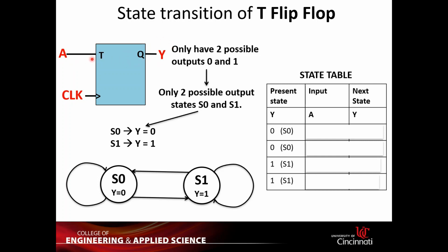If your input equals 1, it will flip. 0, hold; 1, flip. Piece of cake. So that means if I'm at S0 and my input is 0, I will hold the state and go back to the same state.